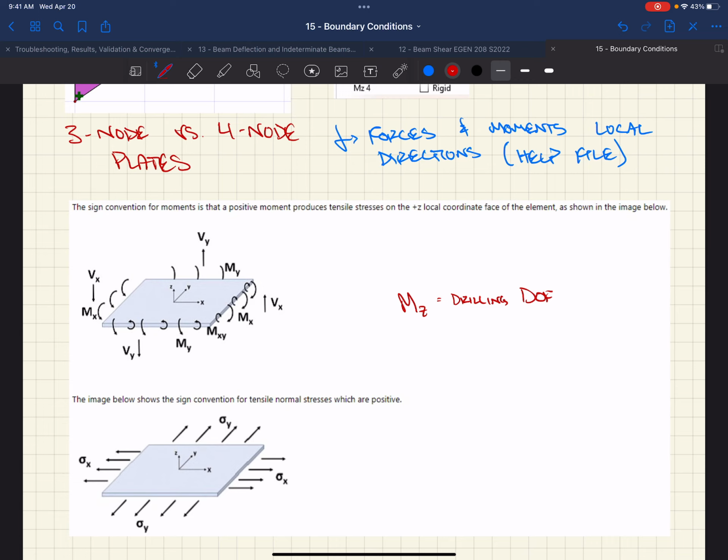It screwed me up for the first couple of years working, because I printed this off and it was on my wall in my office. I can't remember who brought it to my attention, but I dug into this and I was like, oh shit, because validation wise, you'd start looking at things, you'd say, all right, what's MX, right? And it's perpendicular to the direction that you would expect it to be. So if I had a slab that I was designing that spanned between 2 joists, I'd assume that the dominant direction was in the short direction. I'd be showing MY and I'd be like, what the heck? It's like 0, right? And then the other one, and so then you start understanding that the sign convention is different and you just have to keep track of that.